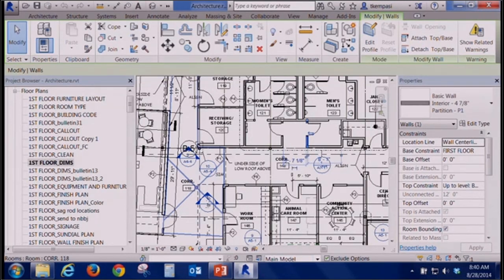If you're just doing real quick design studies, I looked at it this way, I want to save that one, look at it a different way, just do a save as version 1, make another change, save as. A lot of times that's the most efficient way to do it.